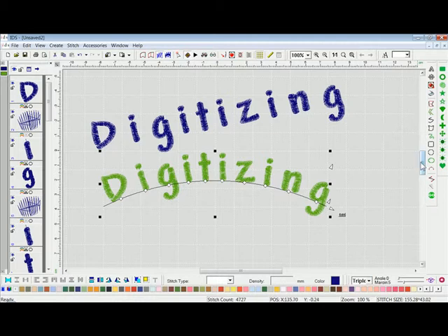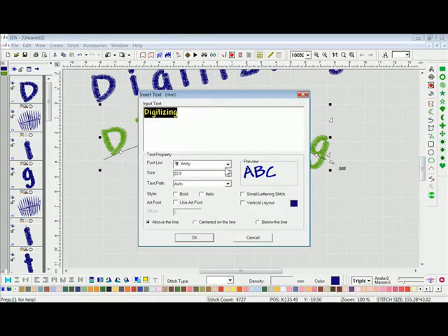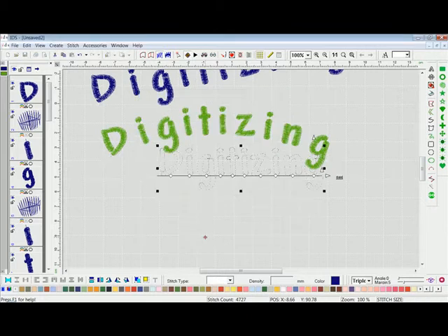With the next baseline, again, we'll go to the Insert Text box. I'll left click on Insert Text, and here we'll change the text path from auto to ellipse. We'll left click OK, and again it puts it on the best fit baseline, but my cursor is a crosshair. With the crosshair, I'll start on the left hand side, and because we are drawing a circle, we will left click, hold, and drag from one corner to the opposite corner. In this case, I am dragging from the upper left hand corner down to the lower right hand corner, and you can see I'm dragging a circle.